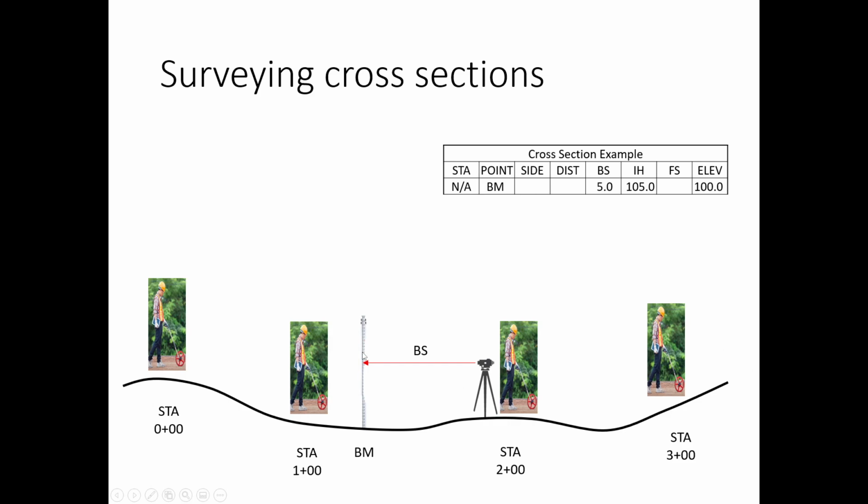So again, here we start off, we want to shoot our backside to our benchmark, and now we've established our instrument height. And so now everything can be a foresight subtracted from this instrument height to establish the elevation of all the other points.